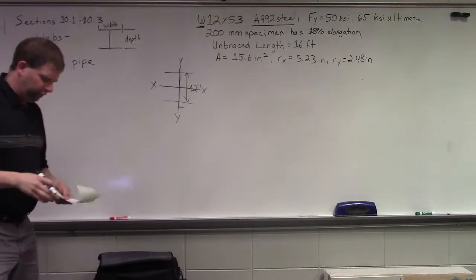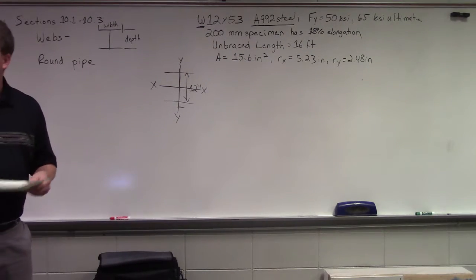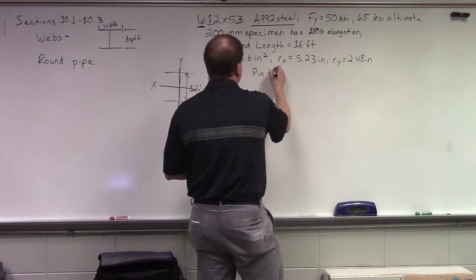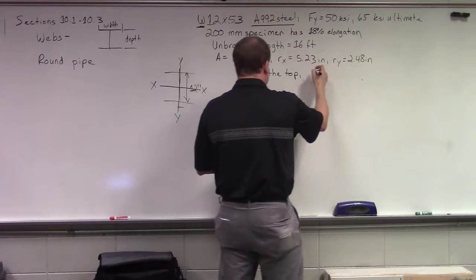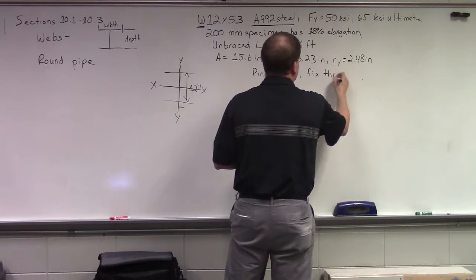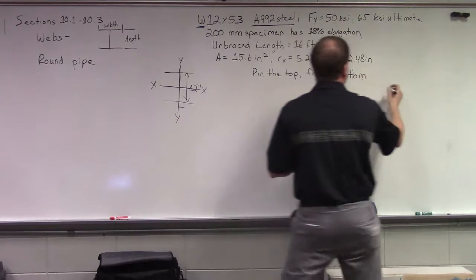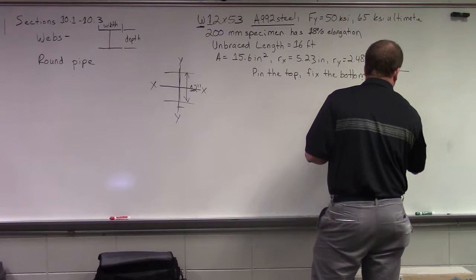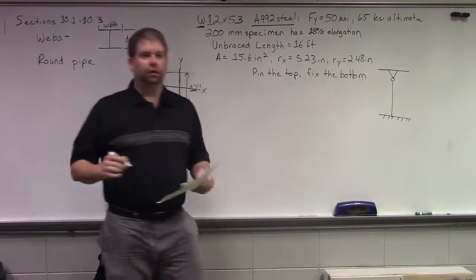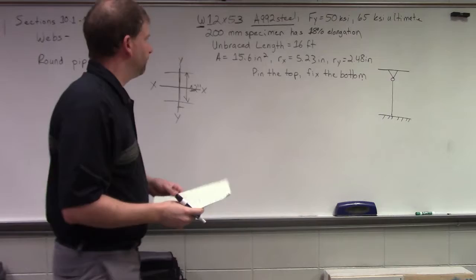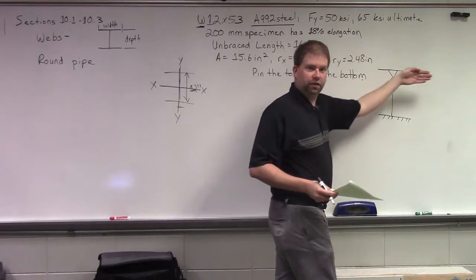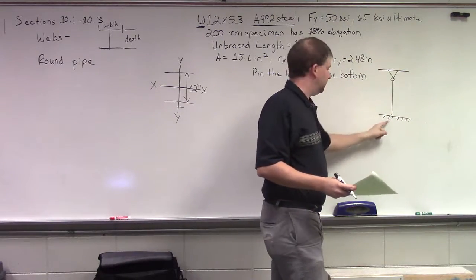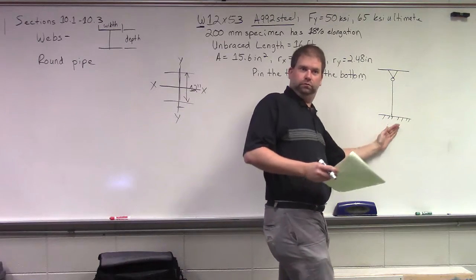So this time, instead of making an assumption about the end conditions, we're going to pin the top and we're going to fix the bottom. This is how our end conditions are going to look. We've pinned our top, so it can't translate, but it can rotate. Down here, it can't translate and can't rotate.